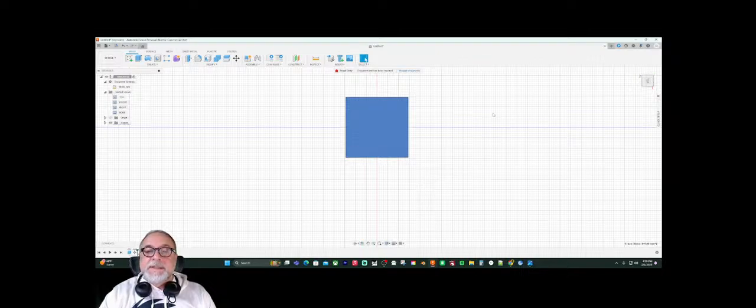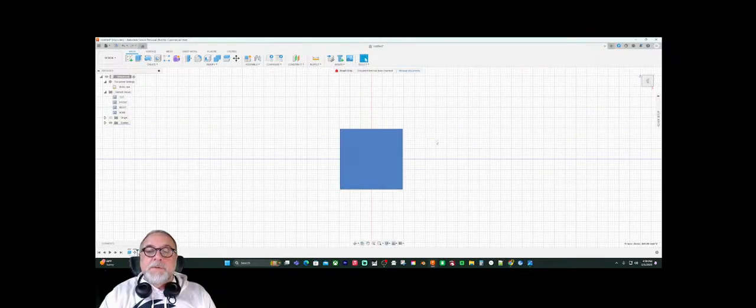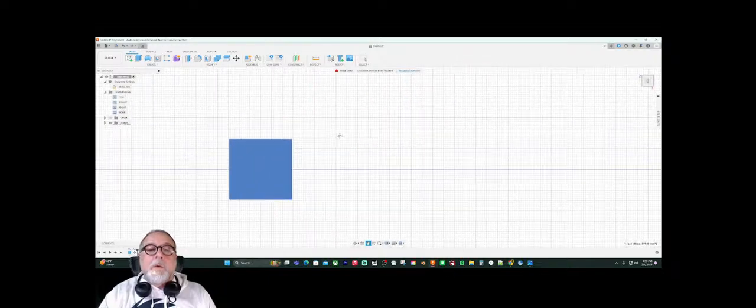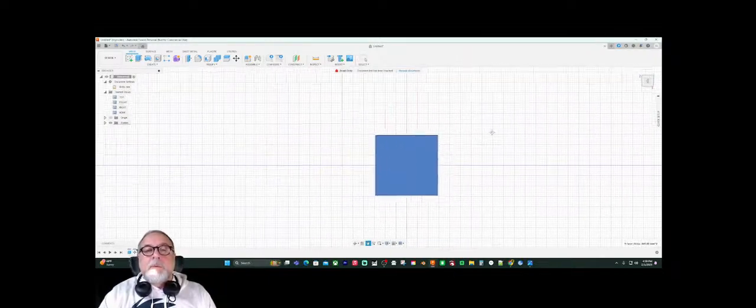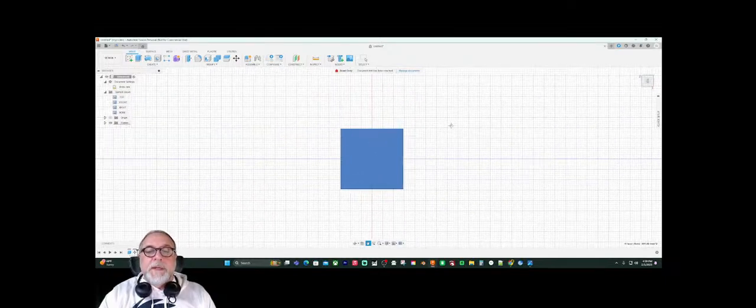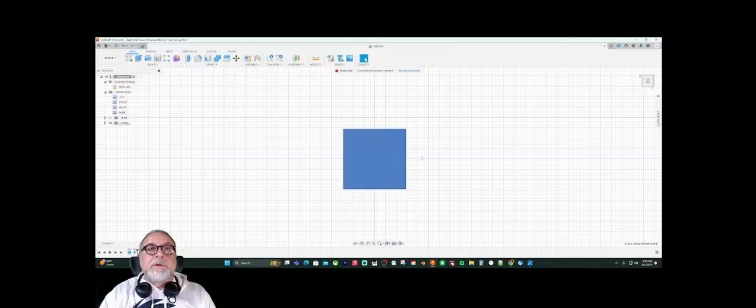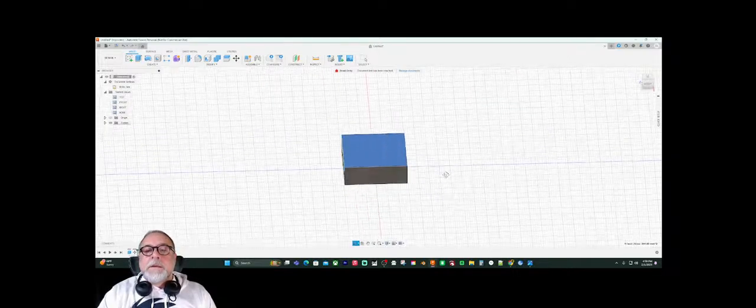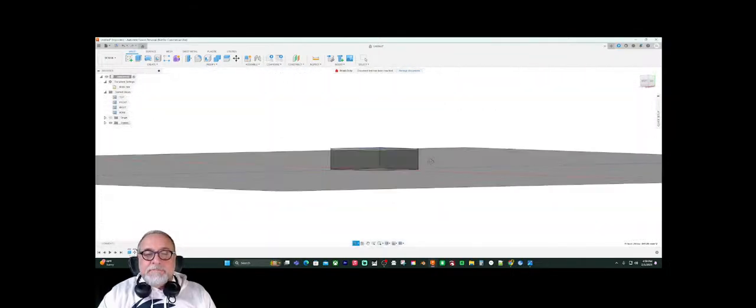And then you just click this again to reorient it the way that you want. Click and hold the wheel button down to move it up and down, left or right, so you can center your image the way that you want.